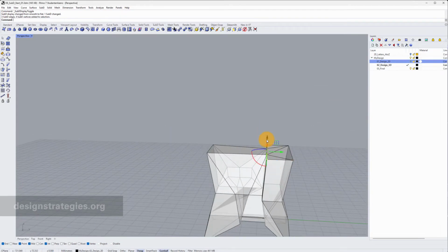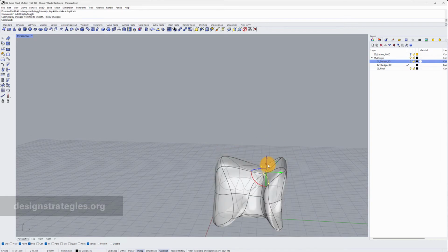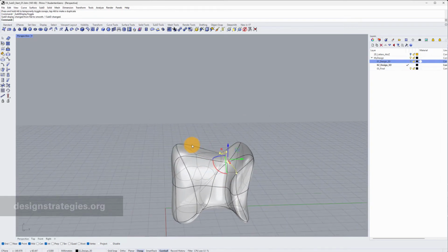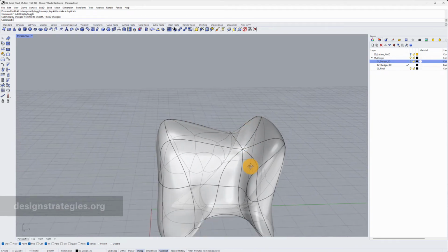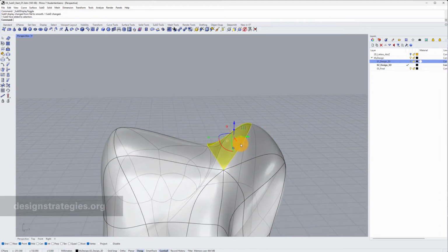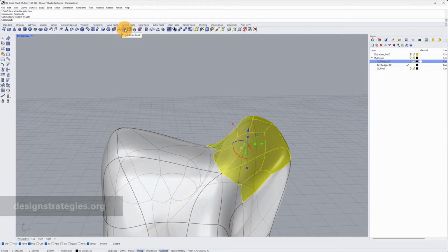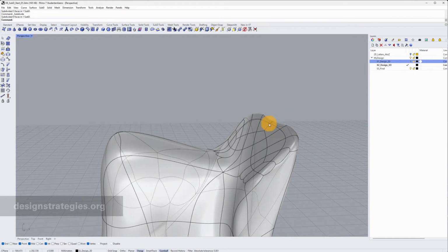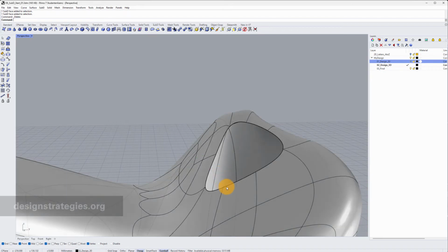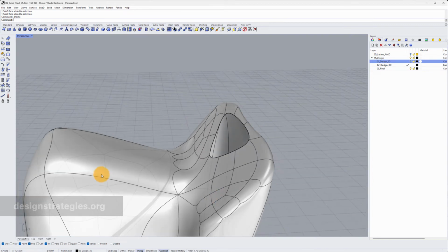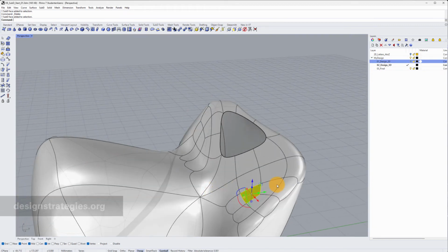Anyhow, it's a little bit of a try on how you would like to change your design. For example, here I move this down a lot, and also see what it does regarding my design. And if you remember what it looked like, I had some holes, some extruded holes. I'll just show you how I did this. If I select these surfaces, I subdivided these surfaces to a point that there were areas, for example like this part, which I was able to delete. Somewhere like this, and then I have my first hole, and the same thing on the other side, or for example, somewhere like this. And I just delete this.